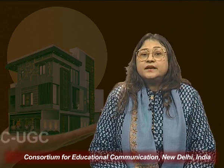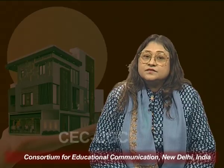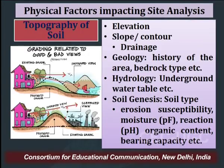The first aspect, which is the topography of the soil, basically means the elevation of the site. That means at what altitude the site is present. What is the slope of the site? What are the contours that are existing? These aspects will impact the overall drainage condition. That means when the rain falls, how the water is drained out of the soil, out of the site, because the site will have certain undulations. Any site is not plain.